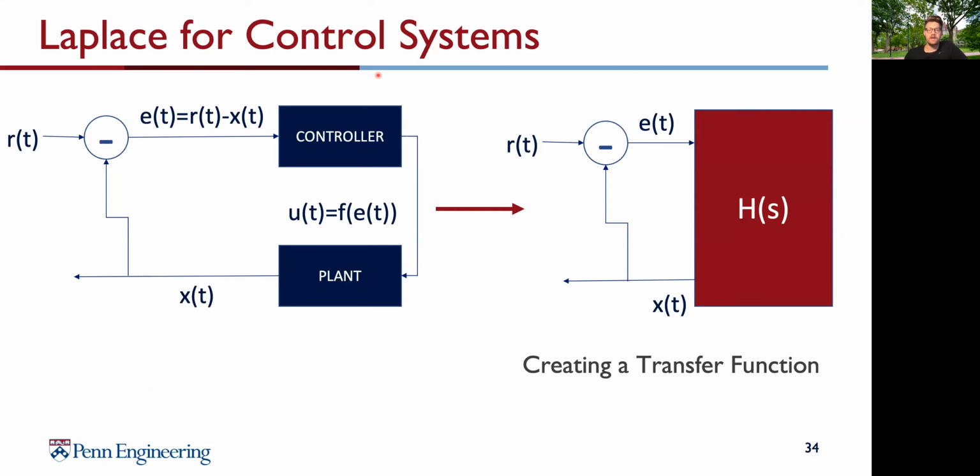So we are creating the transfer functions here, and our control loop consists of several interconnected blocks again. By transferring it to the frequency domain, we can describe the whole system with one transfer function only. We have displayed it here in red.